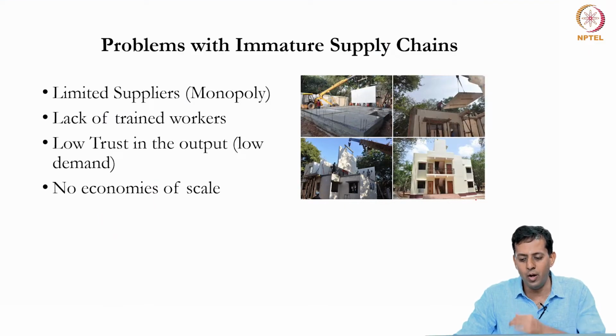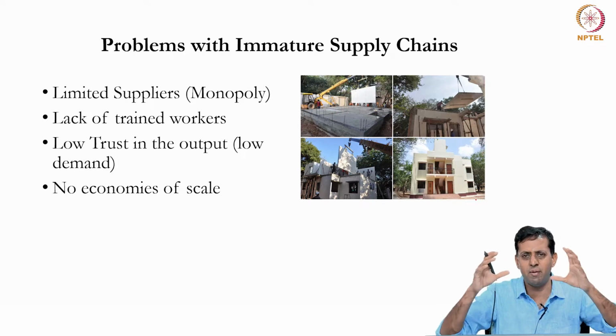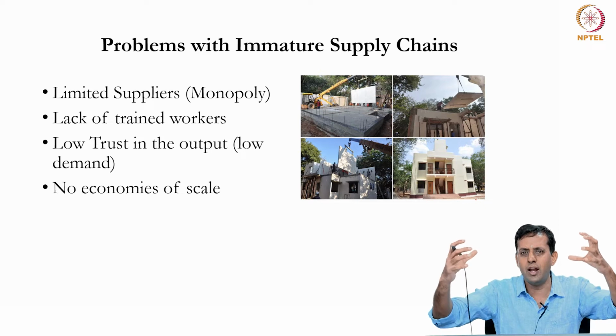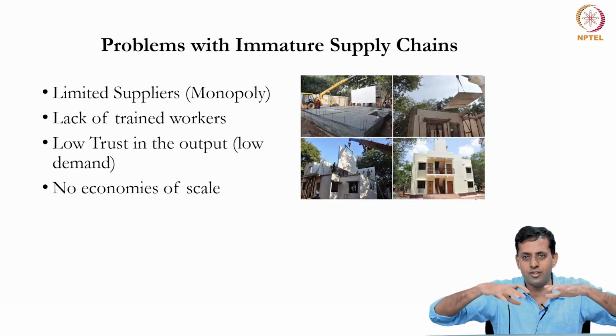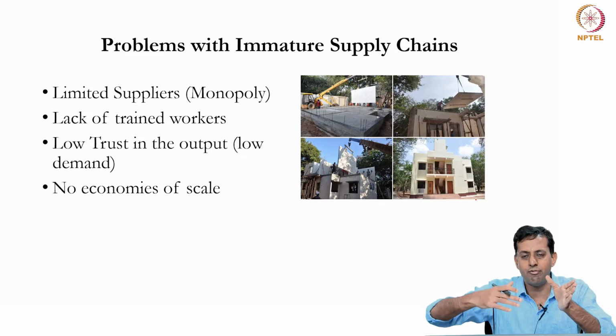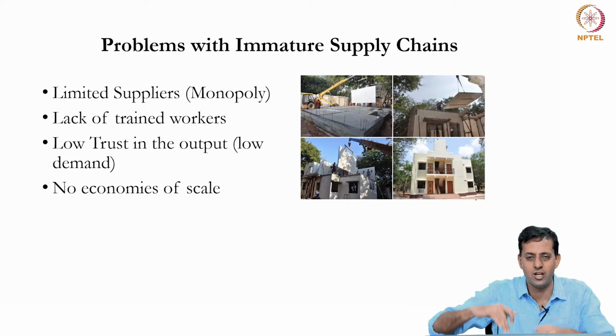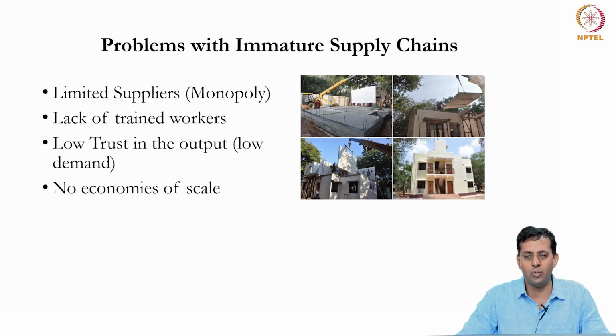At IIT Madras, we recently used a technology called glass fiber reinforced gypsum, GFRG, to build a building on campus. GFRG comes in the form of panels. You get a bunch of prefabricated panels, and of course the foundation is a regular foundation, but then you erect the panels. Of course you put some reinforcement and grouting in between the panels, but then you connect them and you get your building. So we actually built a G+1 building in 27 or 28 days, very, very quickly because it was prefabricated.